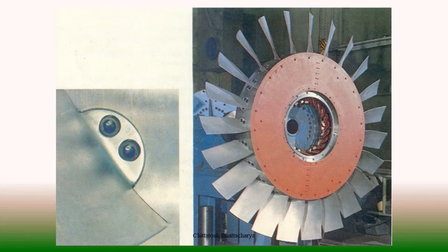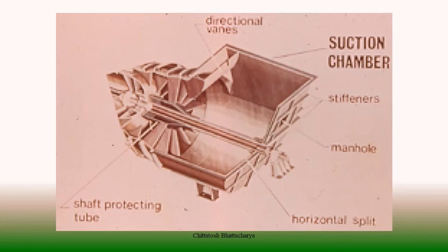Inlet guide vanes are also arranged similar to the blade pitch control type of arrangement. There is a turnbuckle arrangement. This turnbuckle arrangement is fitted with loading cylinders, pneumatic loading cylinders. From the remote position, these pneumatic loading cylinders can be operated, and with this operation, the turnbuckles tilt the inlet guide vanes together in the same range.